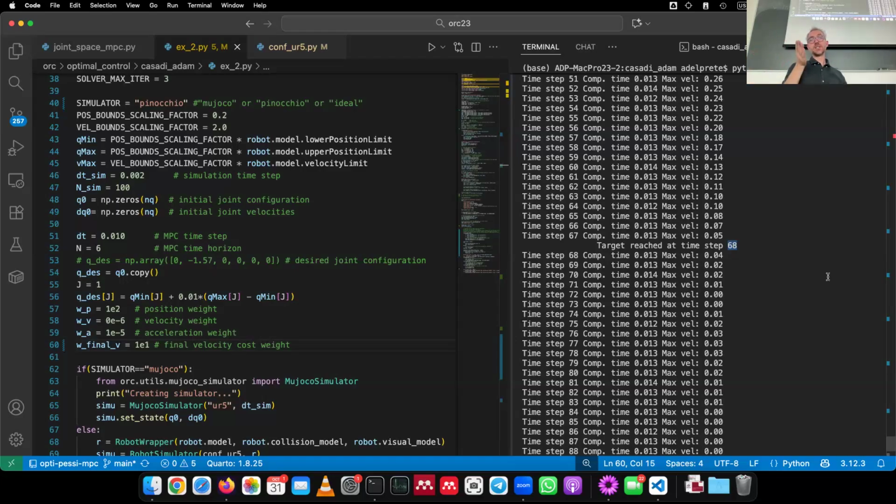And the reason why it is control invariant is because we are assuming that the robot has sufficient joint torques to compensate for gravity. And that's the case for almost all robot manipulators. And if that's the case, if you are in a configuration, whatever, with zero velocities, you can remain in that configuration forever. So you're control invariant because you can remain inside the set. So that's basically the one we are always using. We can just expect the robot to stay there once we are in it, because the torques are high enough. Yeah.